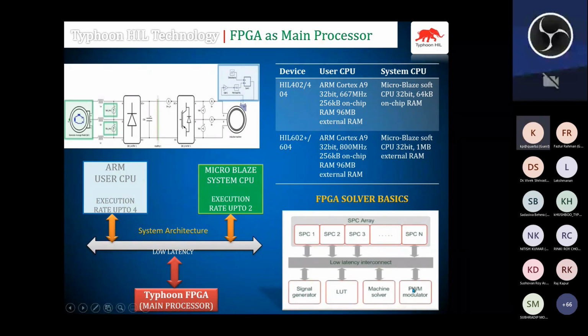So this is the multi-channel triangular PWM modulator, which can be used both internally to drive the internal converter models and externally through the digital outputs. It runs on FPGA internal clock, typically 150 megahertz, and features a built-in dead time period. And again, the number of the PWM channels depends upon the configuration we are using, with 20 nanosecond PWM sampling time, 500 nanosecond simulation time step with third generation, and 200 nanosecond simulation time step with fourth generation.